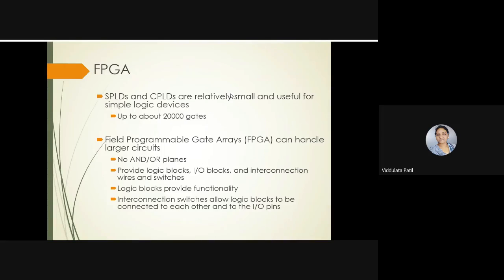Okay. Now let us move further, and now we are going to discuss FPGAs. Again, FPGA is a programmable logic device. But whenever we consider programmable logic devices, the first that come to mind are SPLDs and CPLDs, that means simple programmable logic devices and complex programmable logic devices.